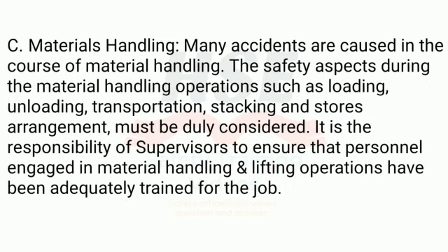C. Materials handling. Many accidents are caused in the course of material handling. The safety aspects during the material handling operations such as loading, unloading, transportation, stacking and stores arrangement, must be duly considered. It is the responsibility of supervisors to ensure that personnel engaged in material handling and lifting operations have been adequately trained for the job. The material must be inspected for abnormalities such as jagged edges, burrs, rough or slippery surfaces prior to initiate handling. The materials, which are greasy, wet, slippery or dirty, shall be wiped dry before handling.